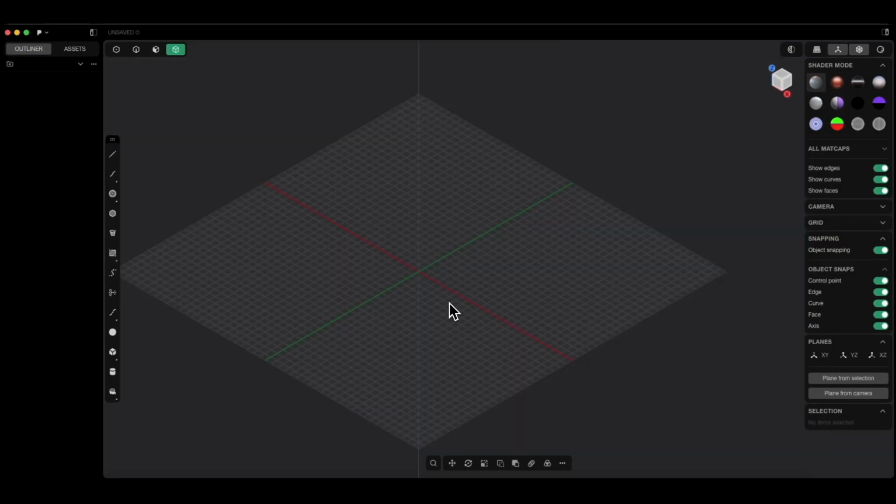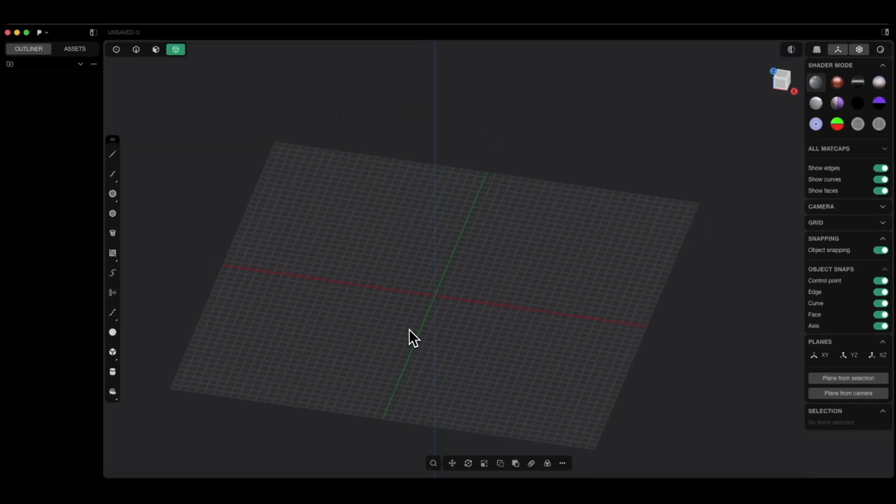In the previous example, I showed you the mirror operation quickly. Now we will go over this operation in a bit more detail, and it can be applied to both flat geometries and solids. First, I will show you it on flat geometry. I will create a circle of any diameter here. And now I want to get its mirror on the other side of the y-axis, and to do this we activate the mirror operation.